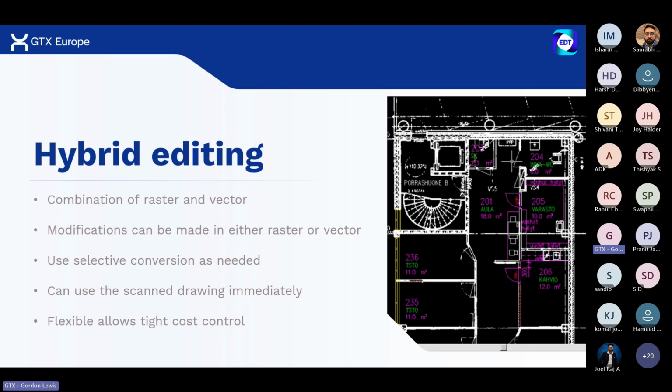So what you then need to do is have a combination of a DWG and a TIFF that XREF and follow each other around. But within the new software that we have, we now have the ability to embed the scanned image into the DWG so that you only have one file that follows each other around.